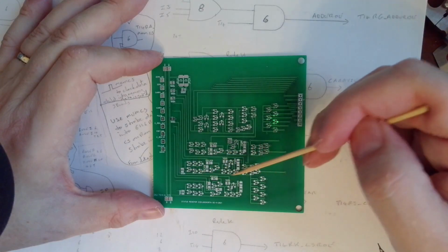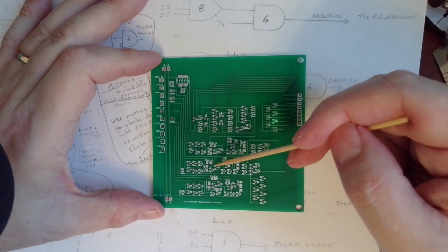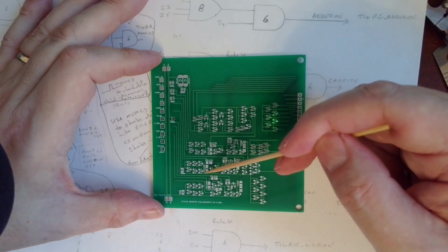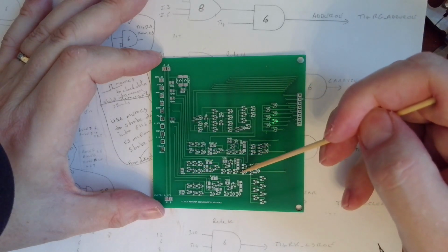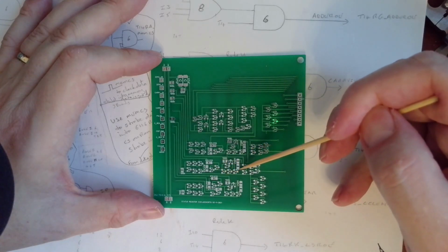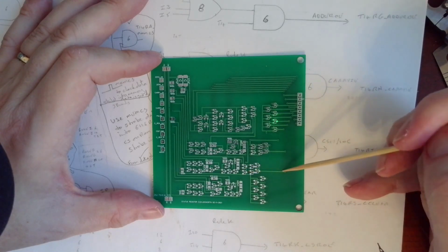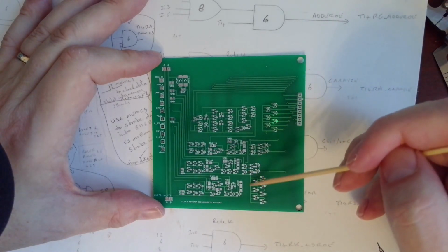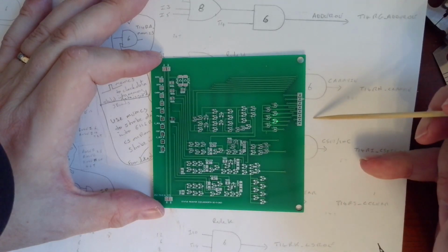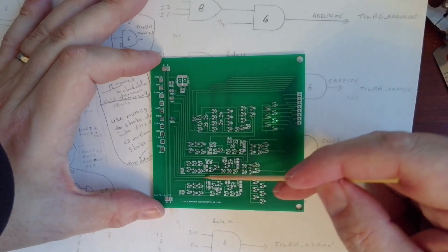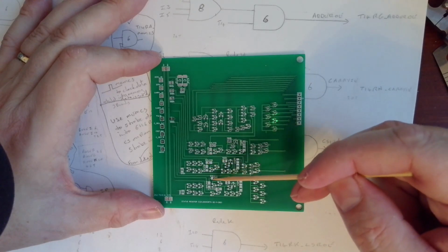Here we've got the carry flag, very similar, except the carry is coming in from over here, and that's the part where it switches in. And there's your AND gate at the beginning to control the switching of this circuit to put into the memory cell here with the C register, carry flag rather. And there's your output switching on to D1, and these 7 transistors here are to pull the other bits to 0 as well. So again, you've got a 0 or a 2 coming out. And this down here is the actual C register. So the carry flag from there will actually be switched into here.